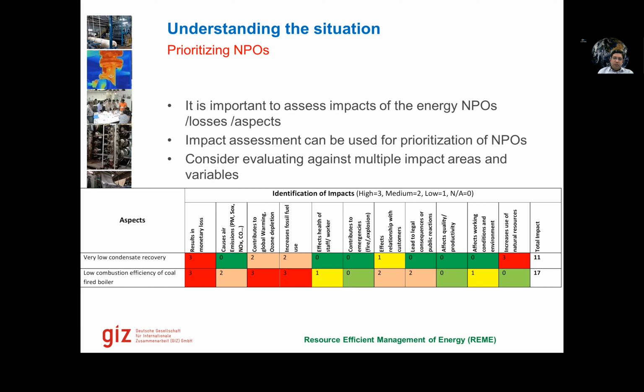And then we multiply this with the number of hours in the year this boiler is operating. So we can tell them how much total amount of NOx, CO, PM, SOx you are emitting. For the textile and garment factories who are using the HIGG Facility Environment Module, it is a very, very critical issue for them, because while filling in HIGG FEM, they also have to give an inventory of all these emissions.